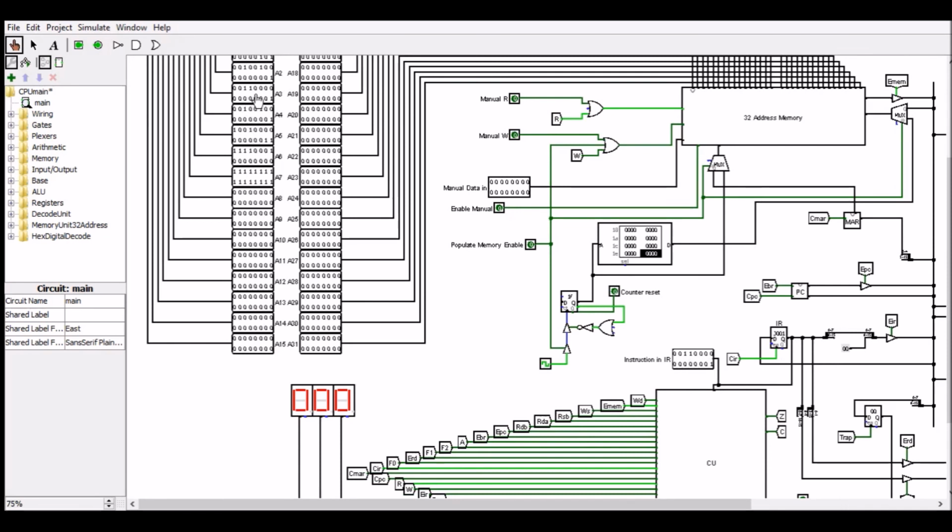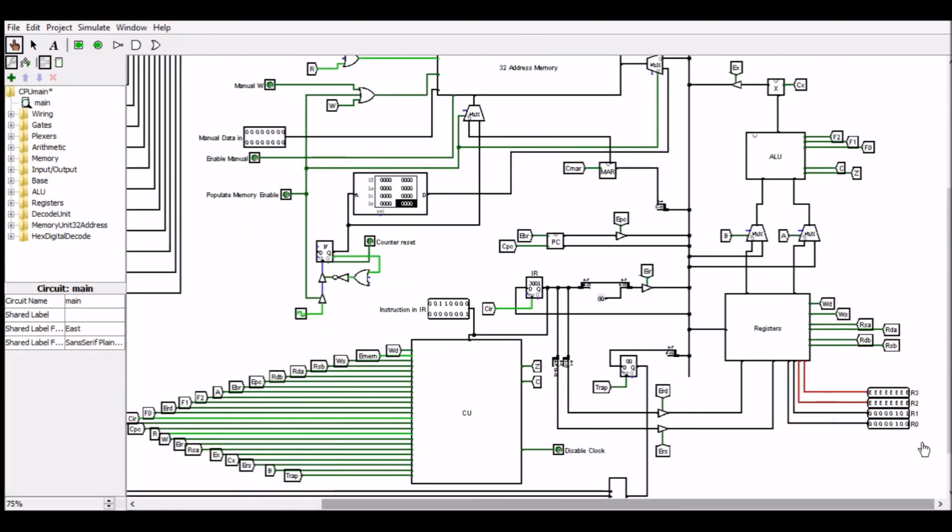Yes, it's a multiply register to register this time, R0 and R1. So we're timesing R0 by R1. And this is to be expected because we're working out factorial. So we have working out the 5 times the 4. So we'll just calculate that. And there we have the result, which should be correct.